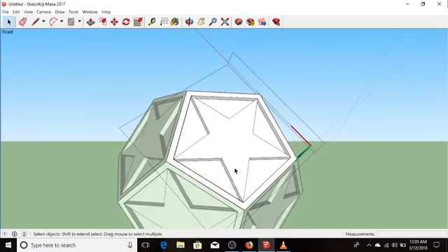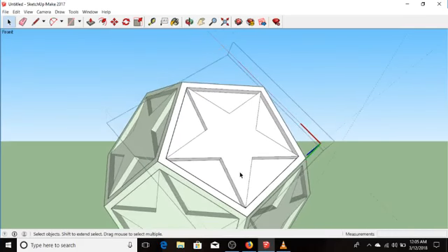Usually you can load textures into here and use the actual textures, but I like to put temporary textures on in SketchUp and then put the real ones on in world. So now, attention Blender people, we're going to texture and UV map simultaneously. You don't have to UV map it, slice it, lay it out. It's all automatic in SketchUp.